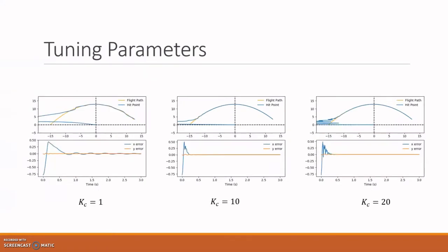So we went with the PI controller, which includes the integral term to close that offset, but it doesn't oscillate. To talk about tuning parameters a little bit, initially we had to answer the question of whether or not we should use two different sets of tuning parameters for both the theta and phi controllers. We decided that since an equally aggressive response is required for both directions, one set of tuning parameters would be adequate.